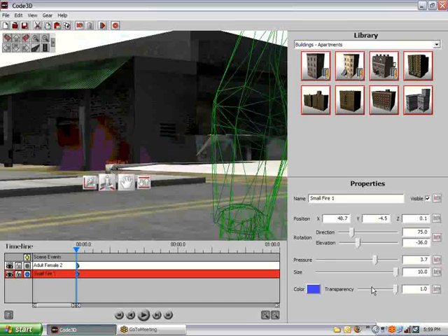As mentioned earlier, you can choose whether or not a firefighter is wearing an SCBA mask as well as the color of his or her uniform and helmet. To do this, you will select the firefighter you wish to change the appearance of, and then you can select your choices for the SCBA mask from the accompanying radio buttons. To change the uniform or helmet color, you will select an option from the drop-down menu.